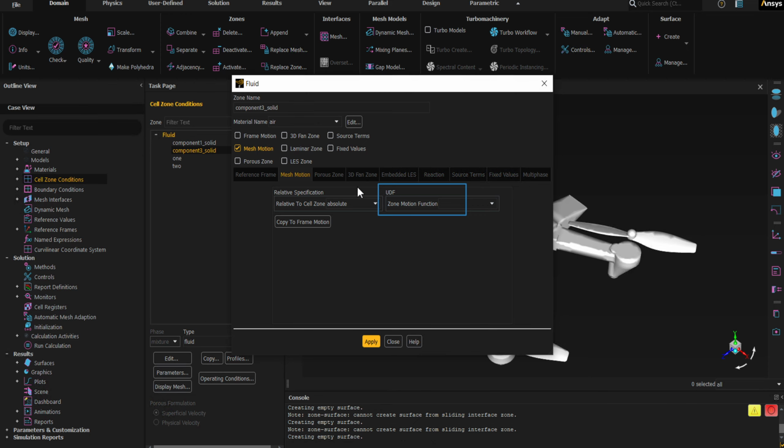We intend to utilize a user-defined function, or UDF, to model the quadcopter's motion during flight. According to the UDF, a forced oscillating motion on the quadcopter is modeled to capture the dynamic stability characteristics. First, we need to import and load our UDF into the Fluent software.